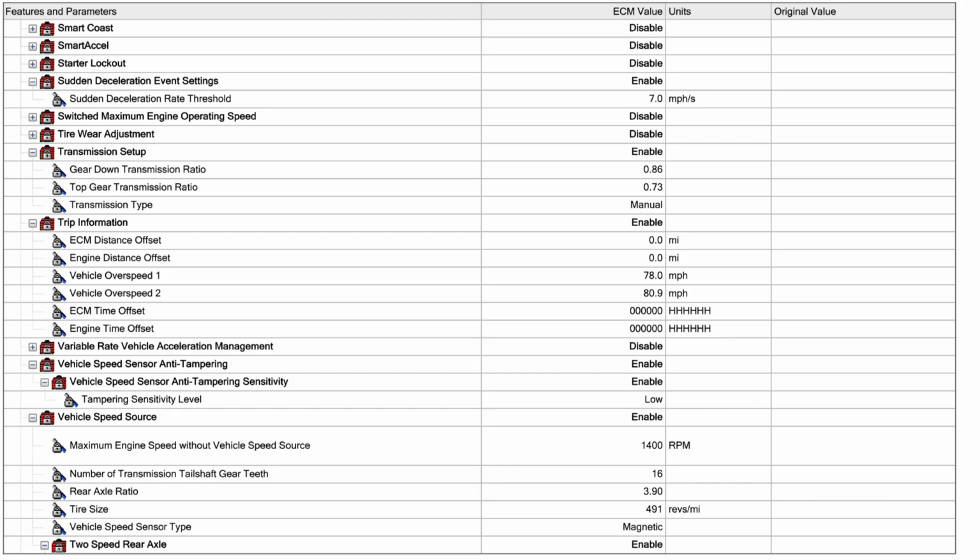Vehicle speed sensor type, magnetic. That just means if you take the sensor and pull it out and you put, say, a feeler gauge that was made out of steel, not stainless, on the end of it, it would stick to it. There's a magnet in it. That's all it means. It uses a magnetic field to read it.